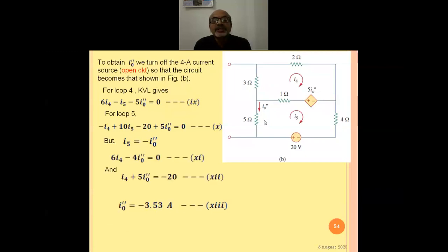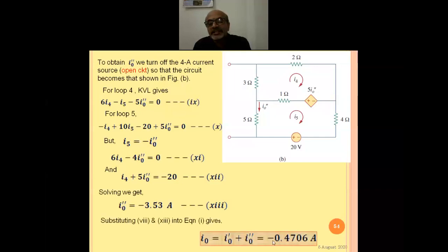Therefore here now I will make use of KCL. So here now I make use of KCL at the point node O, and therefore I can write the KCL, and I will eliminate the number of variables. In fact, I0 dash I will retain as it is because I have to find out the value for this I0 dash. So when you solve these equations, we get I0 dash as 3 amperes. That is the equation number 8.